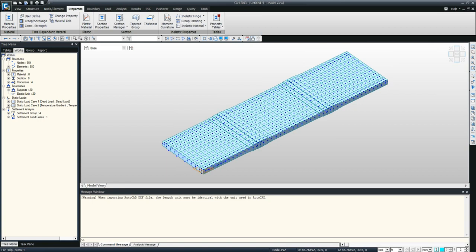Okay, I have a question from Francisco Russo. The question is, how does the composite beam property handle non-composite loads such as self-weight and composite loads like live load? In Midas Civil, you can model construction stages. So that's one way of doing it.